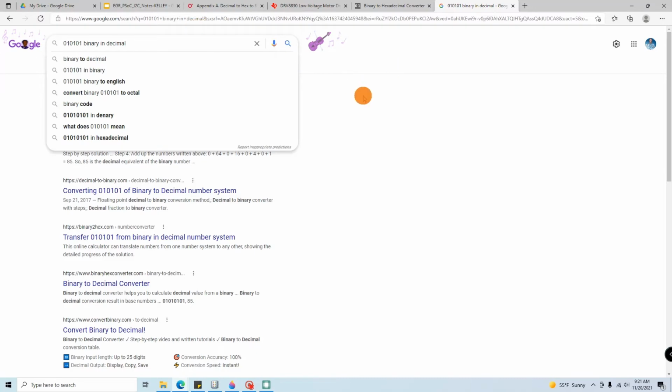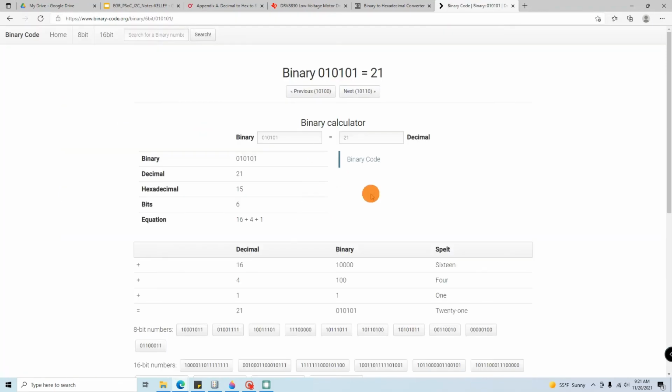So let's say we chose a speed of 0, 1, 0, 1, 0, 1 for my 6-bit speed. Or yeah, that'll be decimal 21. And then 6 bits, that only gives you a resolution of 64, so this will be just under half power. And then for the final 2 bits, I will choose a direction of 0, 1.